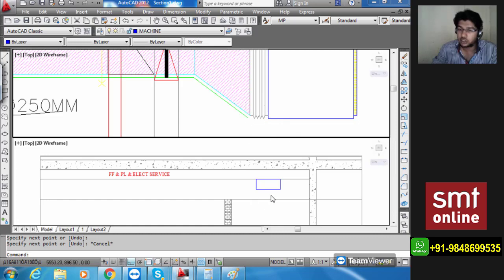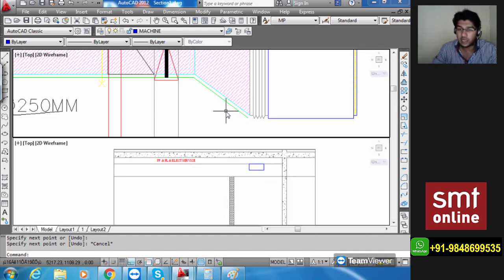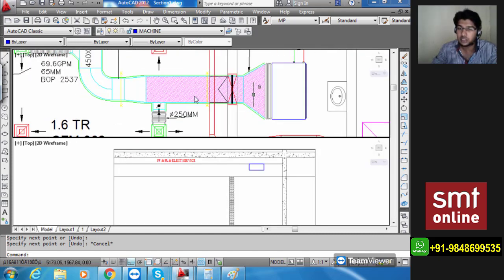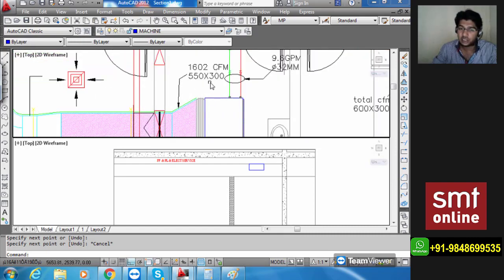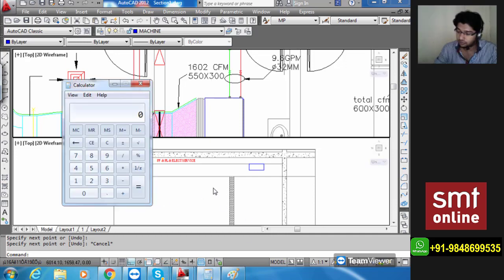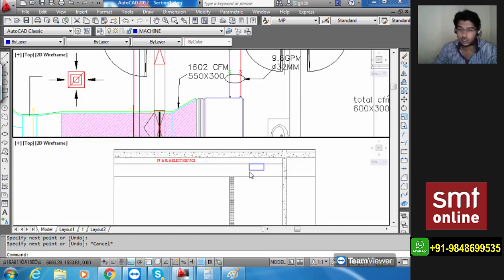So in my section drawing, I will already understand that there is the AHU and there is a canvas cloth, like the SLD drawing. So directly I'll be looking for where my mouthpiece is and how the duct is starting. Now you see the size of the duct is 550. So what is half of 550? 275. Alright, 275 is the actual position.